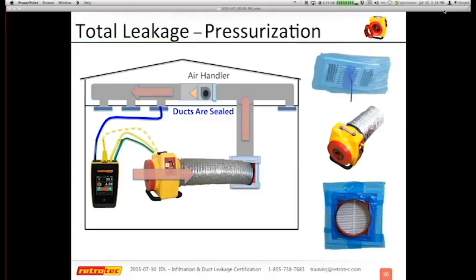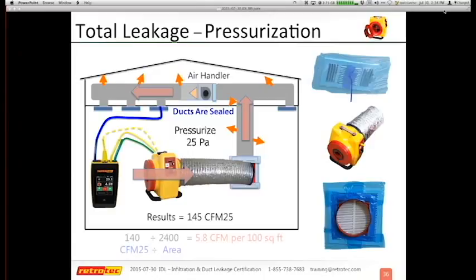And you'll see that sometimes depressurization will have a slightly smaller number than pressurization. That's because air, when it moves through openings, depending on the type of opening, doesn't always have the exact same type of flow through it, as well as sometimes you have small leaks around the duct seals. So in general, don't assume that if you turn the fan around, you're going to get the exact same number. They're usually fairly close, but never identical.